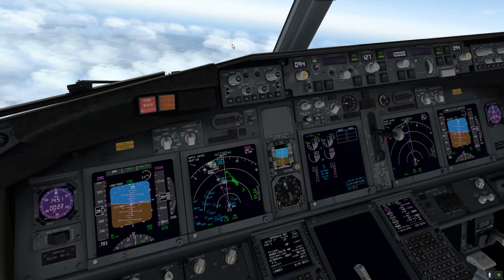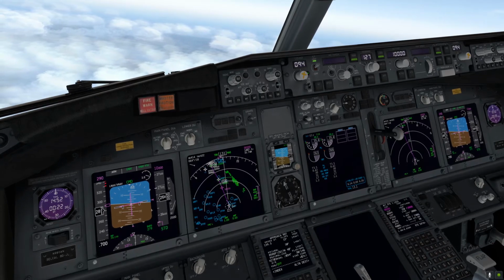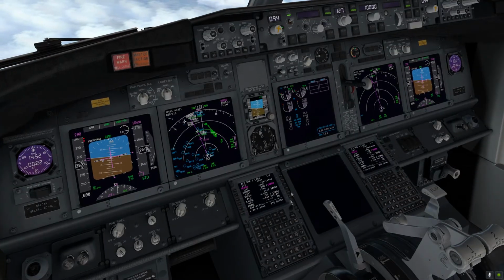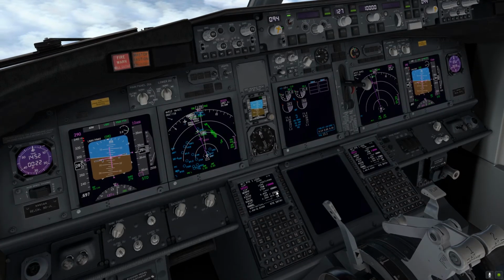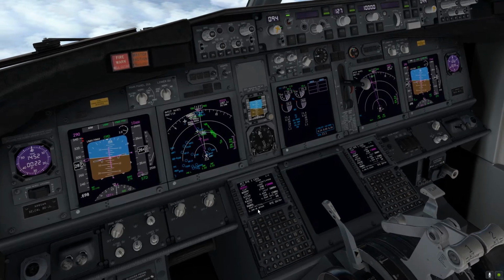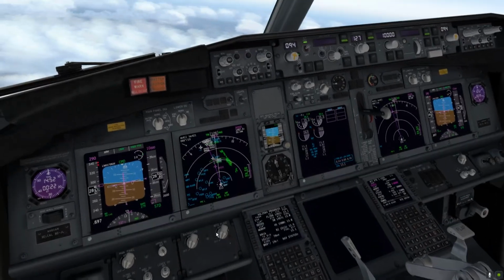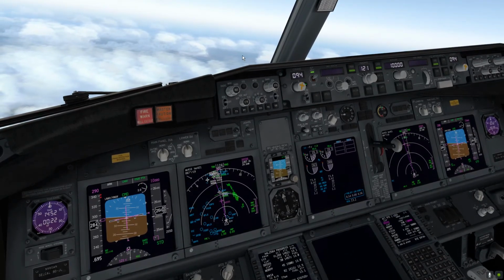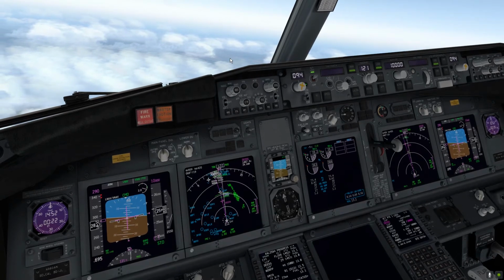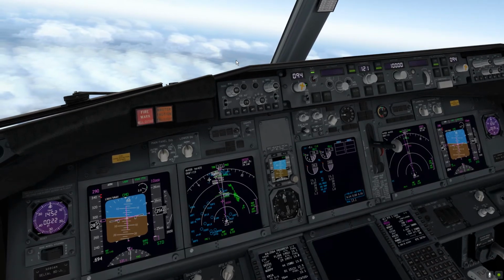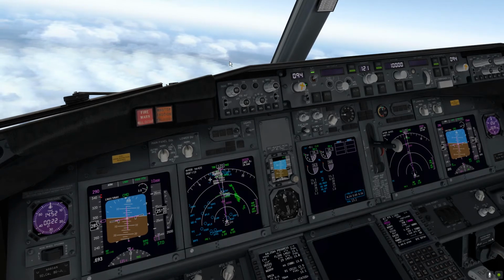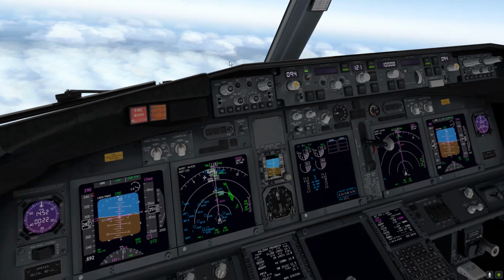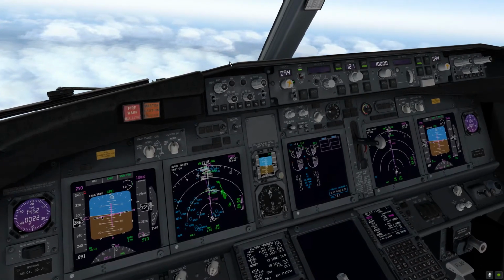and very turbulent areas with mountains and so on and so forth, then we might or we need to adjust some altitude constraints into the FMC legs page to better match the real altitude and to correct the low temperature error and the wind error as well. But today is not the case. It's gonna be a smooth, hopefully smooth straight in approach for this RNAV 08 left.